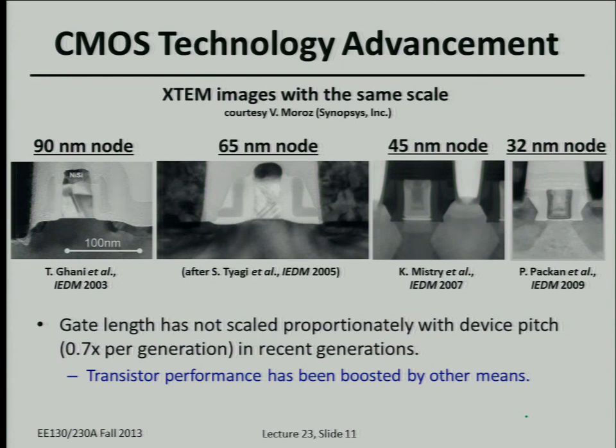And so you can see 10 years ago, the industry was at the 90 nanometer node. So this meant that the minimum half pitch. Pitch is kind of like line-to-line spacing, and so half of that is the number that people use to label each generation of technology. So 10 years ago, they're at 90 nanometer. Today, we're actually at 22 nanometer, and next year, they're going to introduce 14 nanometer technology.